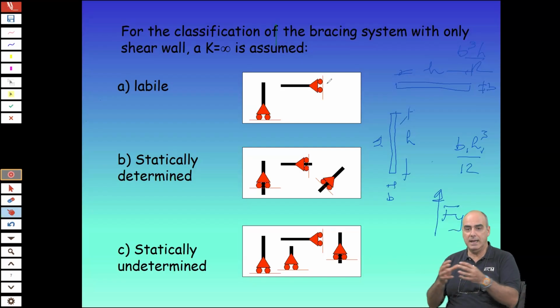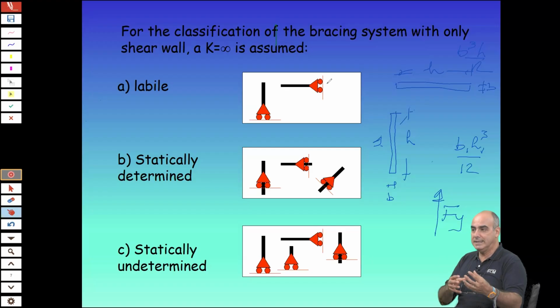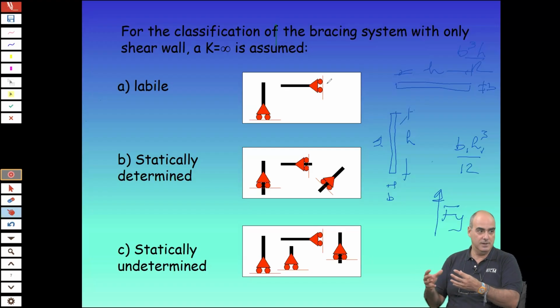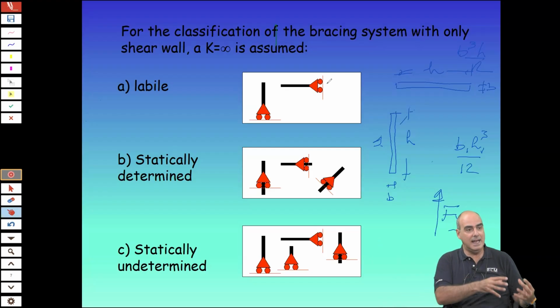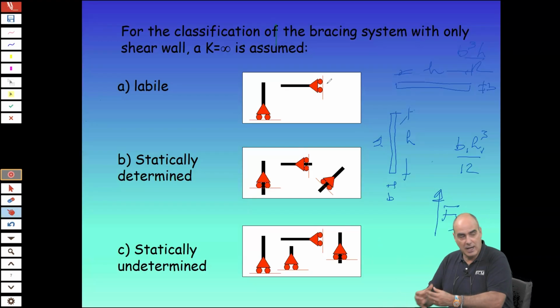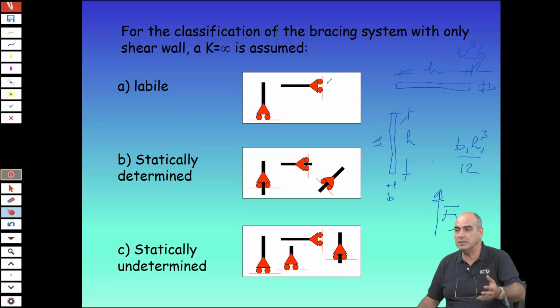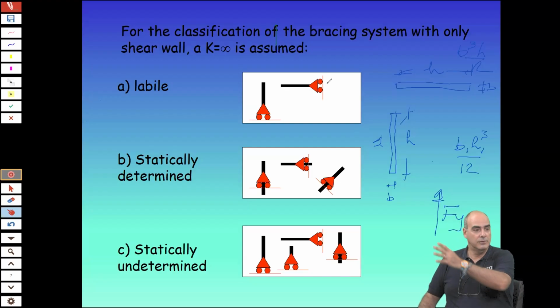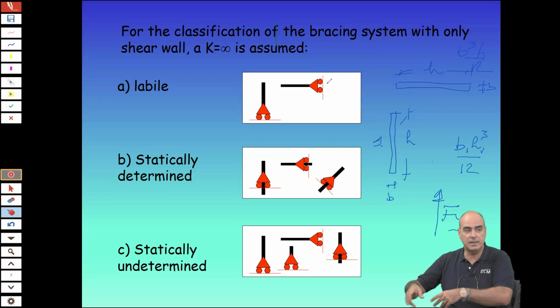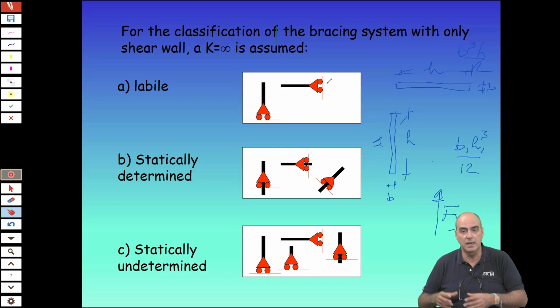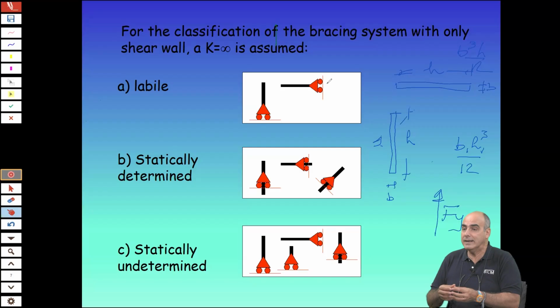So let's merge together material science, degradation science, and structure. That corrosion model that we have seen, let's embed it into a structural design model and see what happens. We have the tool, it's not that difficult, but as Professor Pillai was saying, in most of the cases nowadays we say, oh, for corrosion, just design concrete and put this cement, this water, and so on. No, quality is important. Cover design is important. We also studied in this fact how the permeability to chlorides changes.